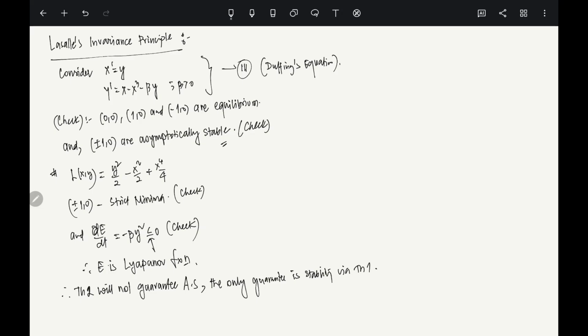If you have somewhere that a Lyapunov inequality fails to be strict, in that case you can use LaSalle. Is it okay? So what is this? It says that, let's say, we define a set S. What is this set? It is the set of all those x in Omega 1 minus b star such that the gradient of L at x acting on f of x is equal to 0.